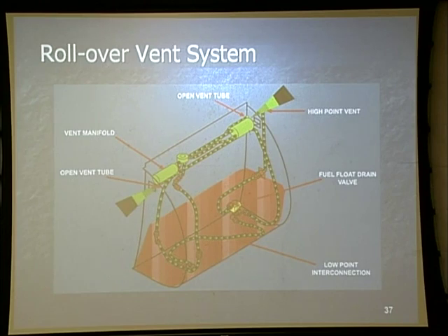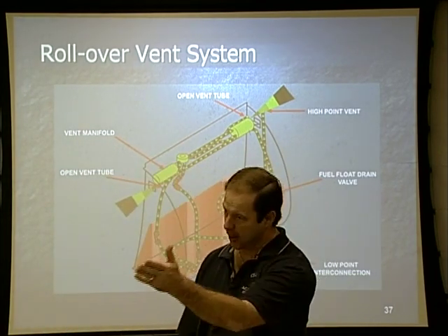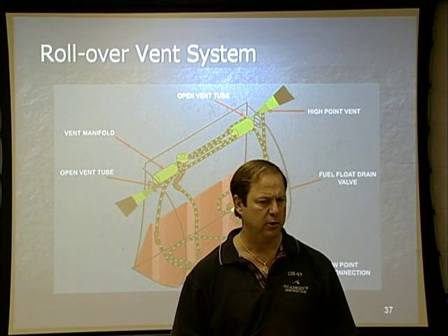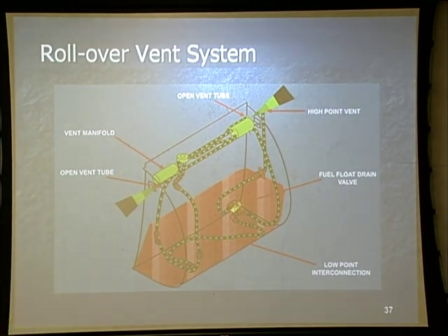But now, we have some other scenarios that we need to talk about. One, where does it actually vent from? It actually vents from the bottom of the aircraft. Good job. Now, why is that important to understand? How will fuel venting manifest itself to us? Well, you probably smell fuel vapor. Smell. That is the primary way that it is going to be identified.